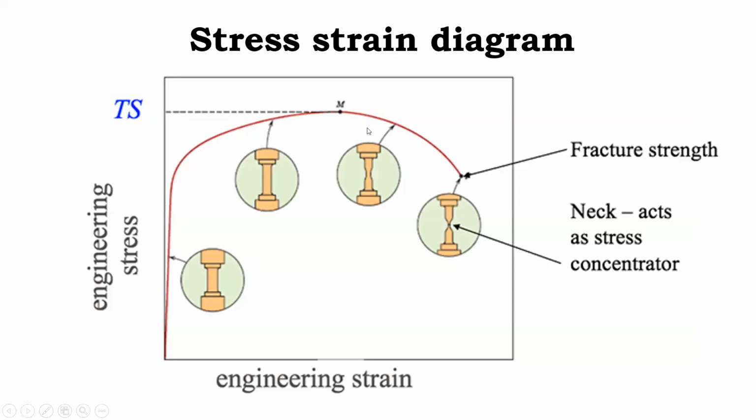Okay, so what we have seen is something like this. Stress versus strain. The tensile test is a very common, simple test which is performed. And this will give us this stress versus strain graph, in which we can see initially stress and strain. As the stress increases, strain is also increasing in a linear manner. So they are basically increasing in a straight line manner, and they are very proportional up to the elastic limit.